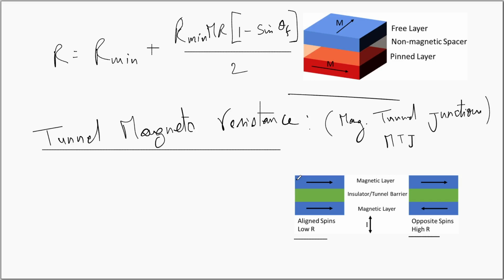In a typical TMR sensor, one of the ferromagnetic layers is free to rotate with the applied field, while the magnetization of the other layer is pinned. Just like the way we have seen in the case of a GMR, here also one layer is a free layer, the other one is a pinned layer. Resistance of the stack essentially depends on the cosine of the angle between the free layer and the pinned layer. In order to fabricate a TMR sensor with a linear response to an applied magnetic field, it is essential that the reference layer magnetization be pinned perpendicular to the free layer.